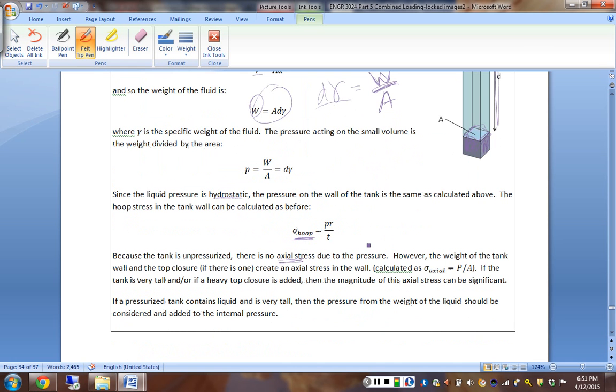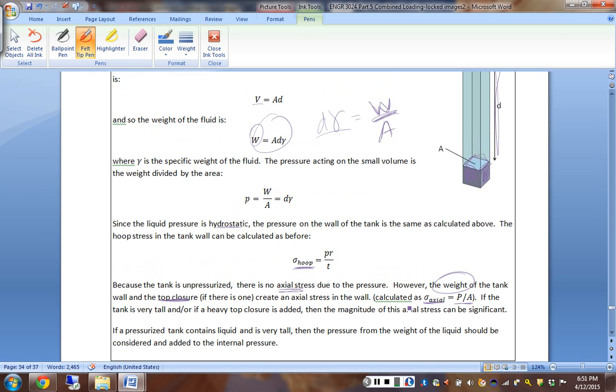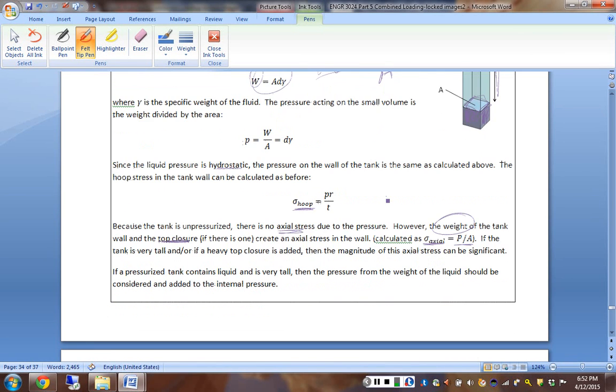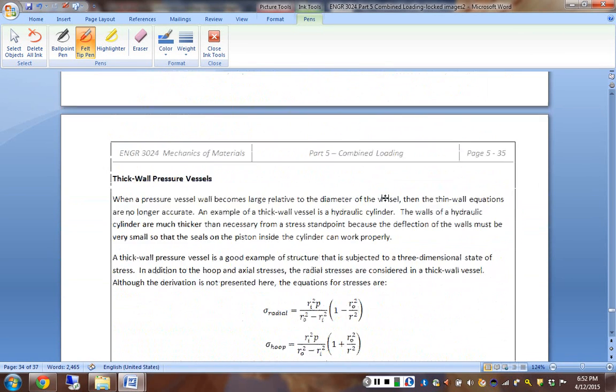If you then instead put a lid on your tank, that would then become a plain axial P over A load. So those are considerations, thinking about if your tank has a lid and whether or not you're going to develop sufficient hoop stresses towards the bottom of the structure that would be a significant design constraint. So that's how to deal with open-topped tanks.